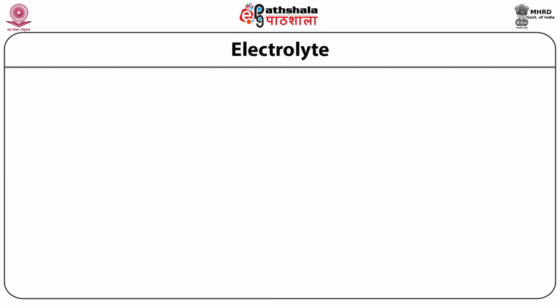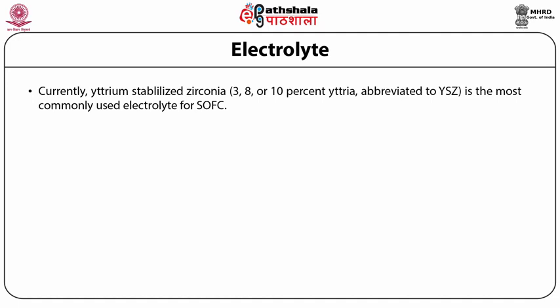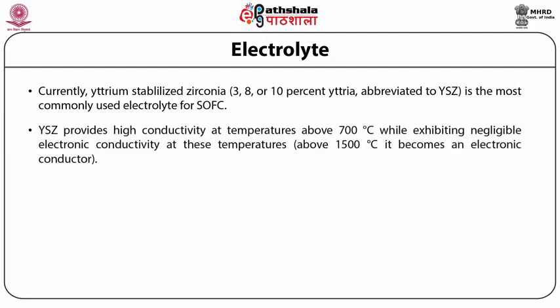SOFC electrolyte. Currently, yttria stabilized zirconia with 3, 8 or 10% yttria, abbreviated to YSZ, is the most commonly used electrolyte for SOFC. YSZ provides high conductivity at temperatures above 700 degrees Celsius while exhibiting negligible electronic conductivity at these temperatures. Above 1500 degrees Celsius, it becomes an electronic conductor.